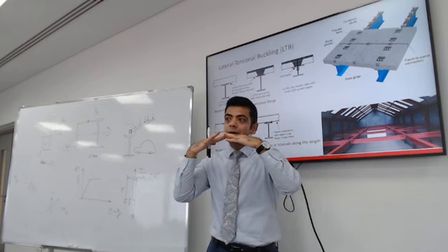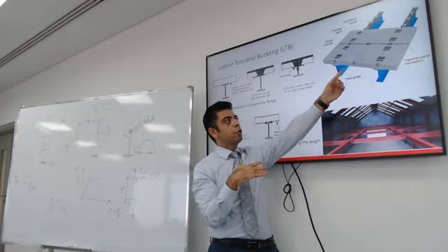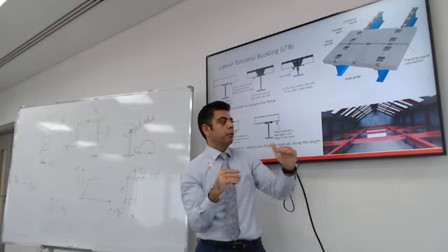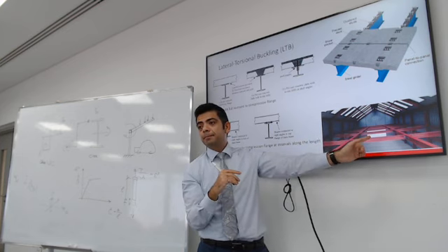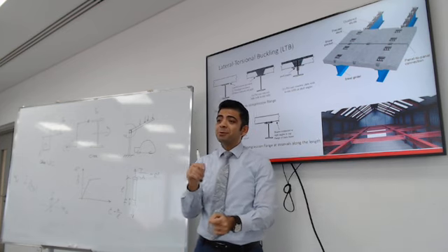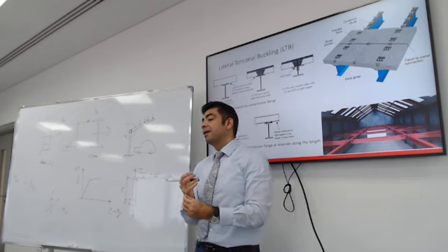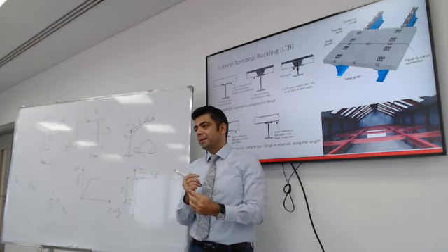It wants to kind of push sideways. So you brace it to the floor. What if you cannot brace it to the floor like that? You design it for lateral torsion buckling. So how do you design it for lateral torsion buckling? Move the joint and the supports.